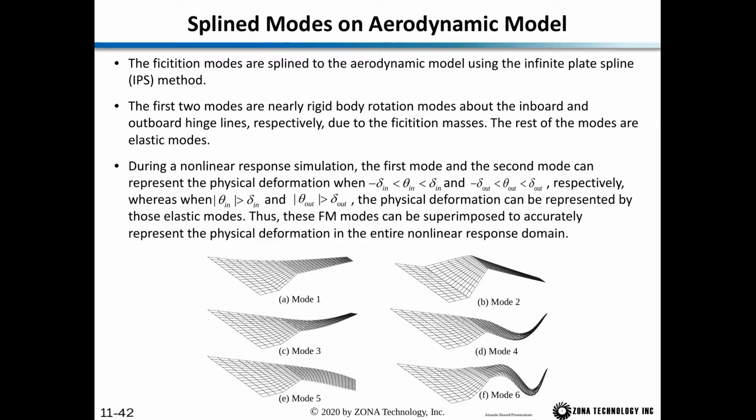And during a nonlinear response simulation, the first mode and second mode can represent the physical deformation when theta in is within delta in and theta out is within delta out, whereas when theta is greater than delta, the physical deformation can be represented by the elastic modes. Thus, the fictitious mass modes can be superimposed to accurately represent the physical deformation in the entire nonlinear response domain.